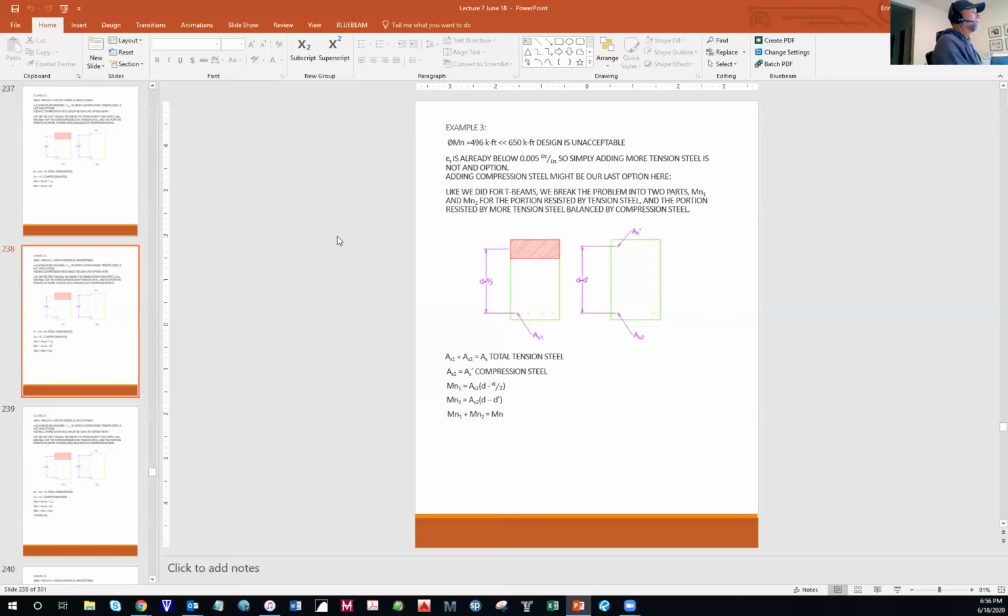When it comes to differing the positive and negative moments and adding them, how does that work? Well, we talked about this before, but I think I'm losing my voice. The way that I do it is you take your load factors and you factor your linear loads. So your dead load has so many kips per foot, you factor that by 1.2.